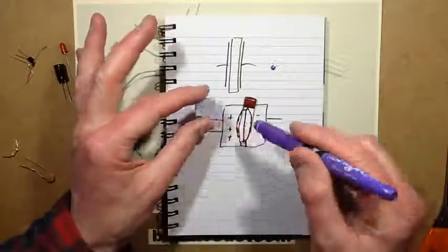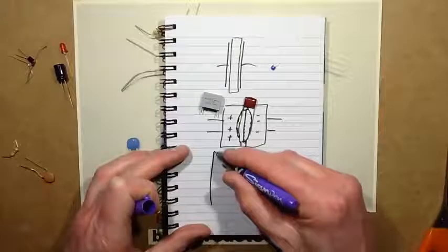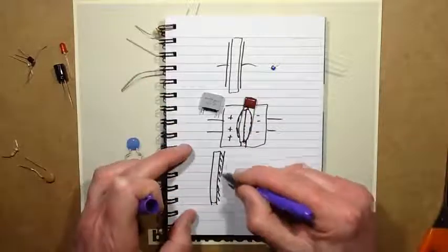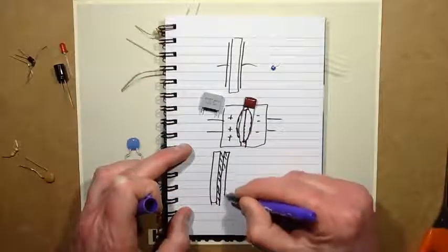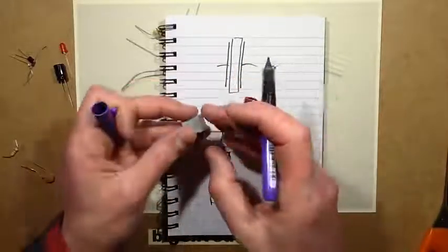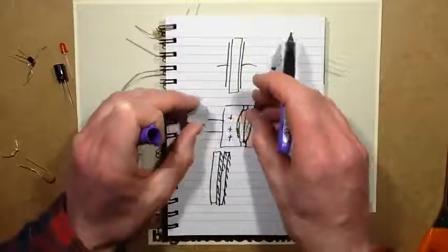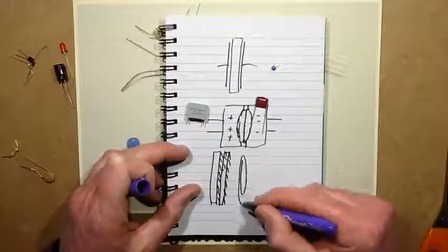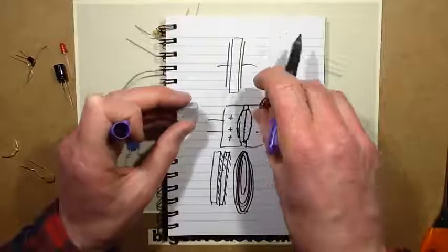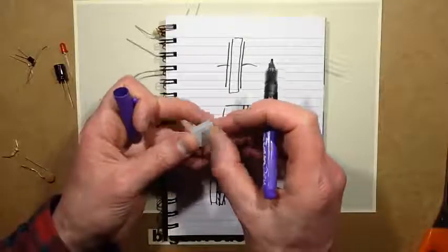And to make this type of capacitor, these are metallized film capacitors, and it's a film that's metallized on one side. And they take two strips of it and they basically sandwich them together. And the plastic aspect of it is the insulator, and the metallization is the electrode. And to fit a lot in a small area, they then actually just spiral. They take a big long strip and they spiral it round into a small area, and that's what creates the sort of larger area. And the thickness of the plastic film itself will determine the voltage rating.